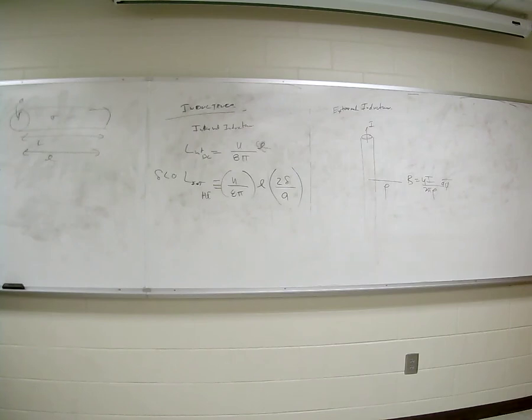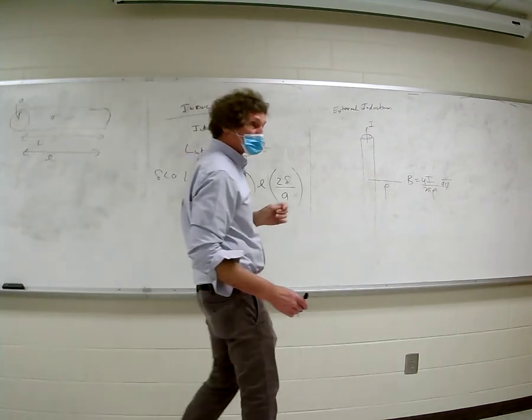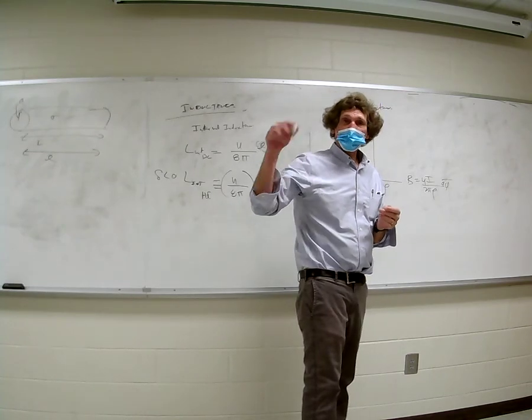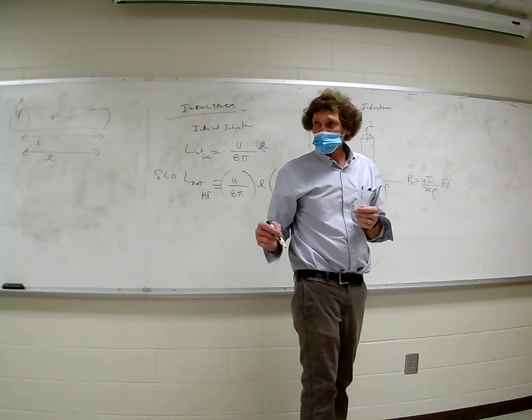Do y'all remember flux linkage, that term that Gross uses all the time? How many have had Dr. Gross in power here? Almost everybody. All right. Well, flux linkage is really, you calculate the amount of flux, and flux means an integral of b dot ds over a surface, and then divide by the current, right? And if you have more than one turn, you have to multiply by n.